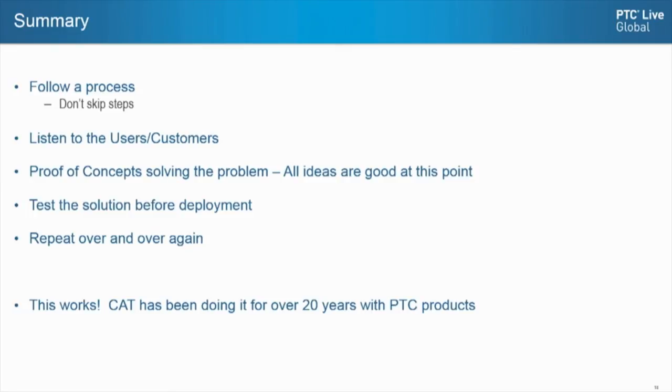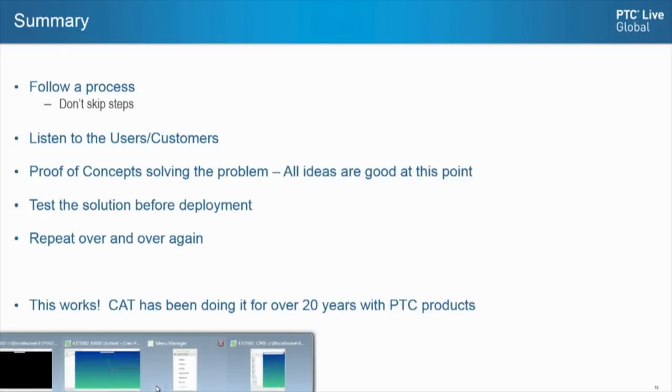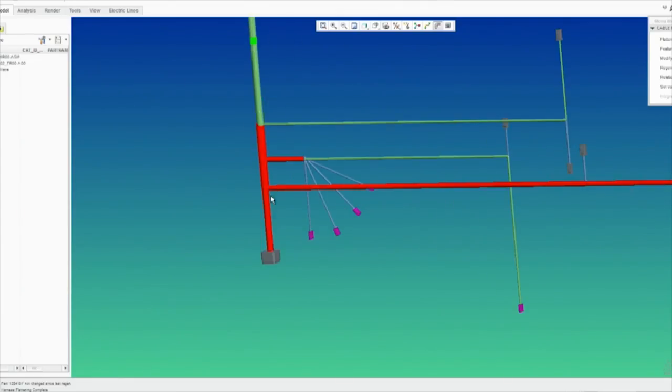So what I was showing you here is a fully packed harness assembly. The wire to-from list is all in here, and the lengths all come straight out of Creo into the engineering drawings. So we don't use a third-party tool. It's all embedded. We don't go in and out of other applications that way. The wire lengths are built into the model. That goes right into our wire to-from list, and we don't come up short.